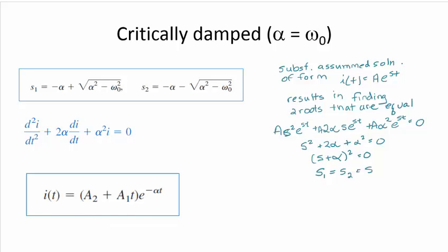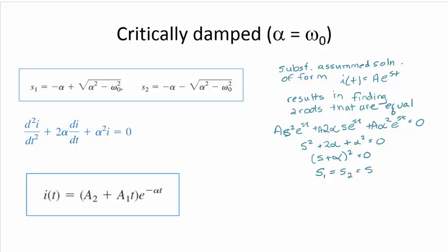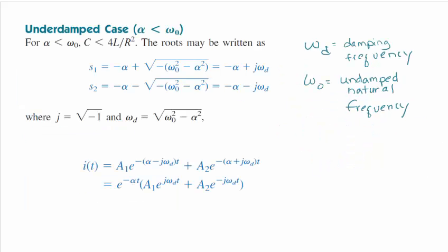So then I went back and summarized my two cases here. It's the same series RLC circuit, two different capacitor values. One gives you the overdamped case in the blue line, and one gives you the red case, which was the critically damped case, with that being the math behind the critically damped case. Now let's look at the other very interesting case, which I actually think is the most interesting one, which is the underdamped or oscillatory case. And this will be a very interesting circuit, so let's go on to it.